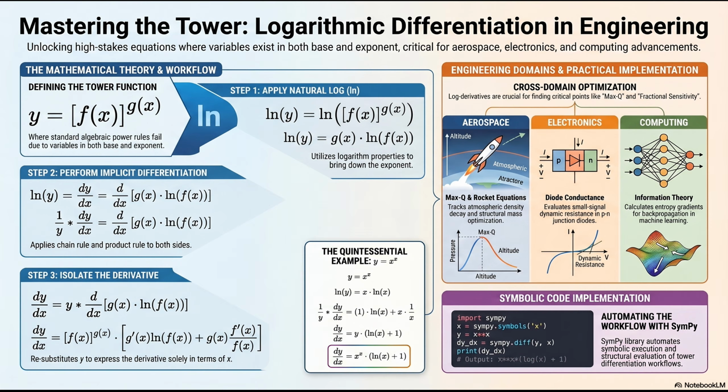By taking the partial derivative of the natural logarithms of both the component and the system output, the formula mathematically filters out all the raw voltages and raw currents. It just leaves the engineer with a pure percentage ratio. So it's basically a mathematical lie detector for finding the weakest link in a circuit. Yes. It isolates the tolerance drift.